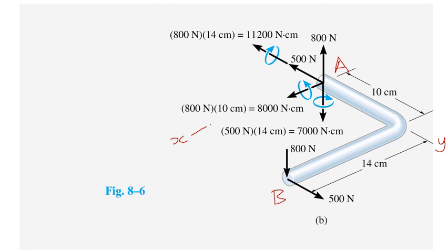And the other effect of this 800 newtons is a vertical force, right? Minus Z. Therefore, the reaction here is 800 newtons in the positive Z direction. So what do we have? We have a force here, which is shearing at this cross section. This is a shear force.